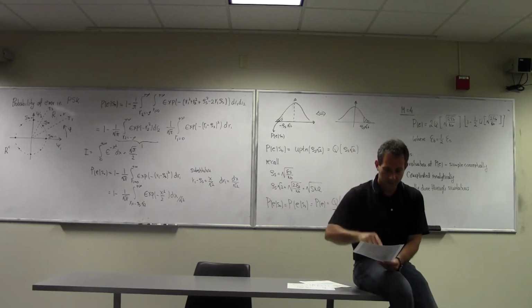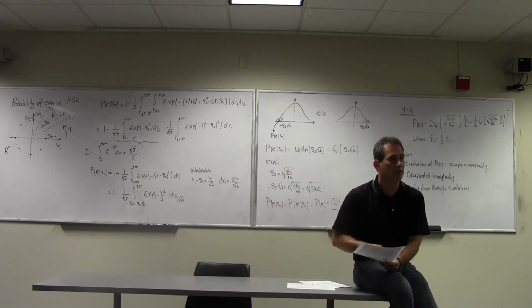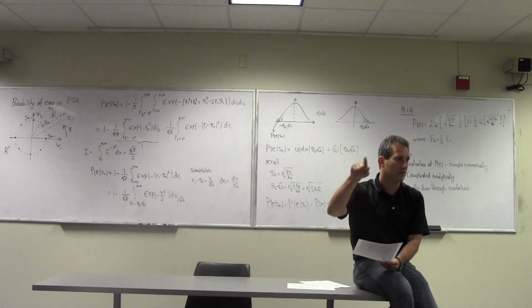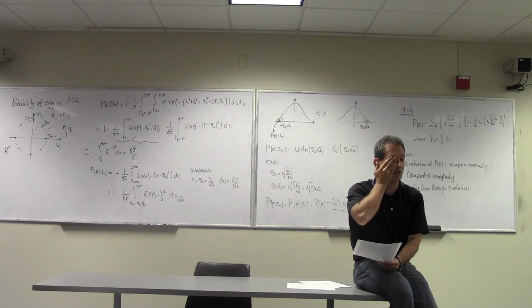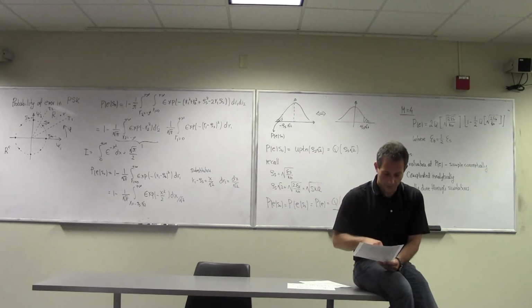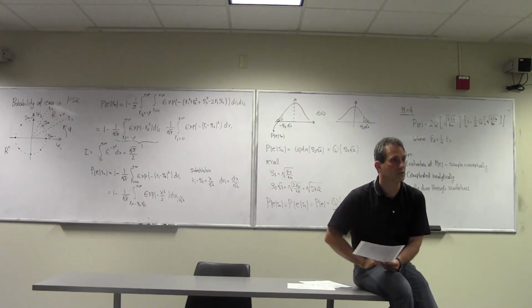Every time I pick a symbol, that's this symbol Sm, I determine sigma, that's the standard deviation of the noise that I have. Then I determine n, which is the sample of the noise, and look at this randn, that's a random number generator with a normal distribution. It is already 0 mean, so multiplying it with sigma generates a random number distribution that has 0 mean and standard deviation of sigma, and sigma is equal to the square root of N0 over 2. If you go upstairs, you can see that that's the standard deviation of the noise.